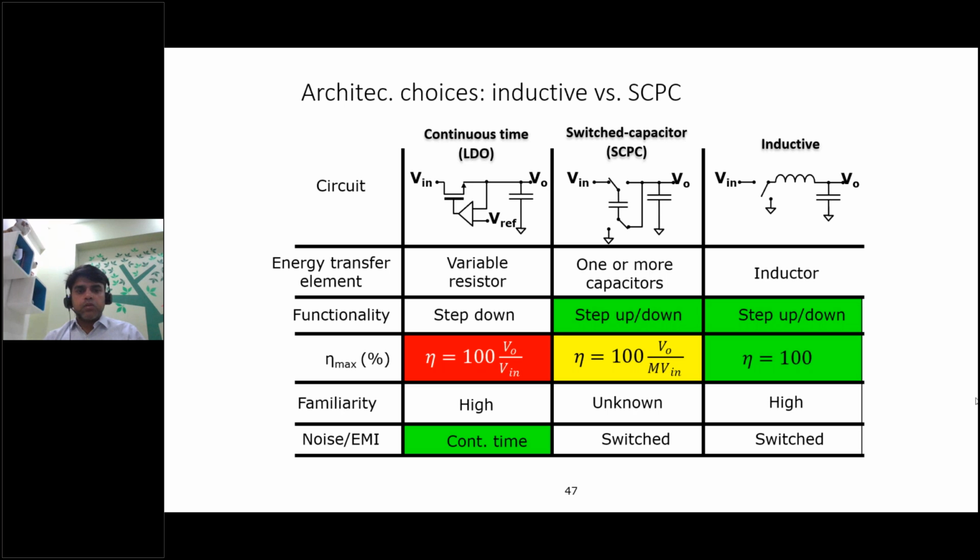That throws some challenges, and to counter them there are standard architectures available, but within those standard architectures you can be very, very innovative and solve the problem. So here, just to convert the real world power supply to a chip power supply, there are three very standard approaches. One is called LDO, a low dropout regulator, and Jaideep talked about that as well.